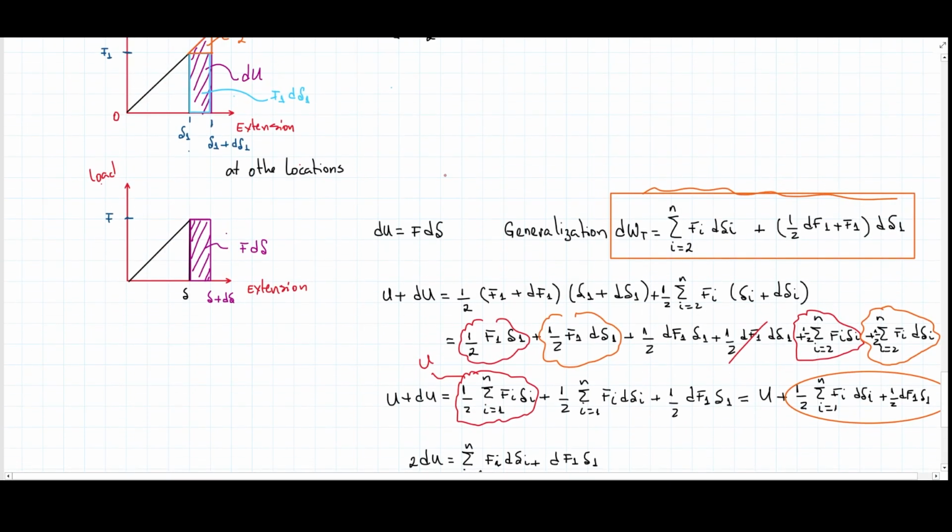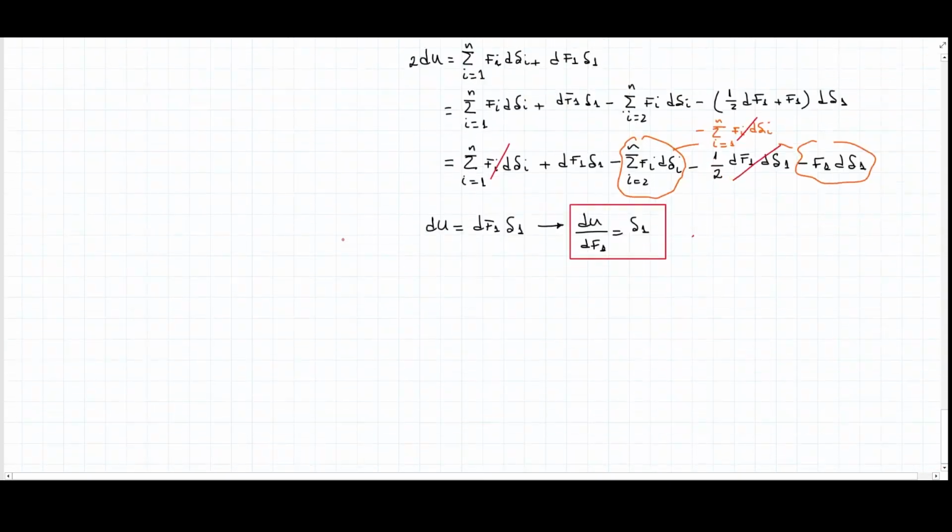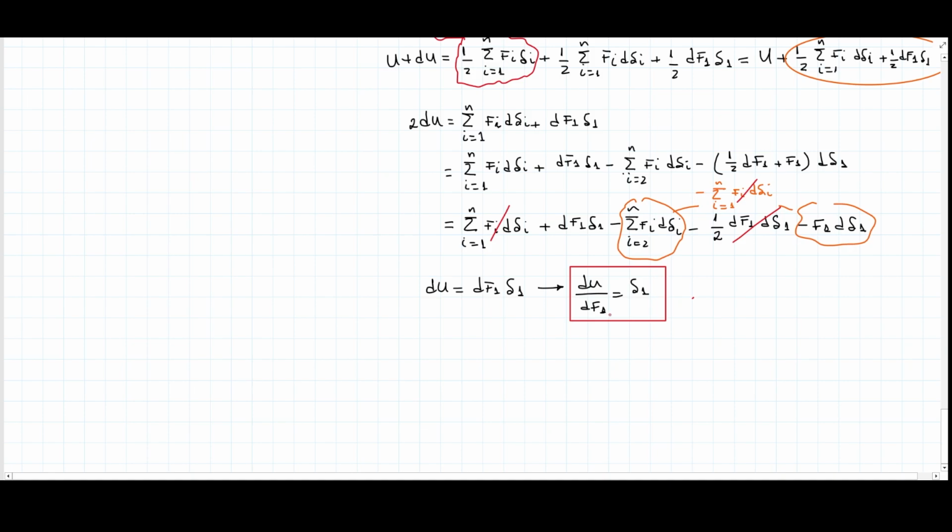And that's what Castigliano's theorem states in this case: the rate of change of strain energy with respect to an individual applied load, just one load, gives the deflection in that position or along the direction of that load. That's what is said in that sense. So where is the application here? Let's take one of the many applications of Castigliano's theorem, and call it application to beams.